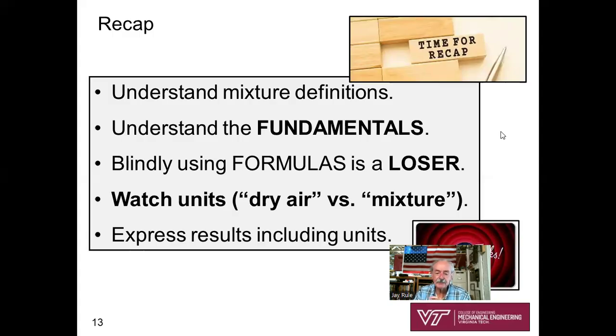For these mixture problems, psychrometric problems, atmospheric air-vapor mixtures, watch your units of dry air versus mixture units. That's a key to success, recognizing the difference between dry air and the mixture of air and vapor. And of course, express results including your units.